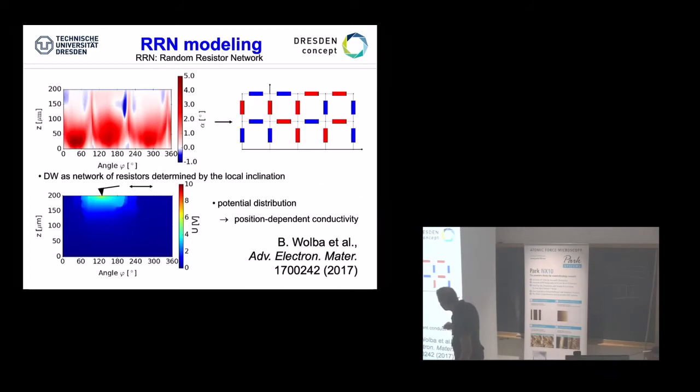And he does then the following, saying, I can now apply either a point electrode, this is my AFM, when I'm doing CAFM on the top, or I can even put up a platinum electrode if I'm doing a really, let's say, macroscopic measurement. So I want to share with you the result: when you apply a local electrode, when you do really CAFM measurements, it's clear that the injected electric field drops within a certain area, and that's exactly what we see. That means mostly, if you put it down up here, at this position the field will penetrate, and yes, we will have a larger current that goes in here and then trajectories through.